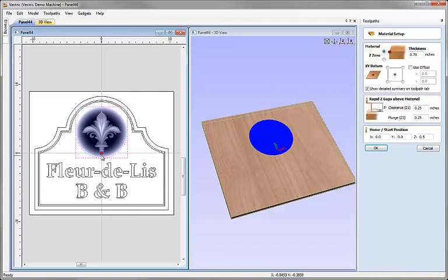If we look, you can see the red square shows me where this position is in the 2D view, and that's actually within an area that's going to be machined away when we do our 3D toolpath. So if we were to machine this 3D toolpath first, then change the tool to do our V-carving, we would no longer have the piece of material here in order to touch off to set our Z0 for the tool that we'd changed. That's pretty important.